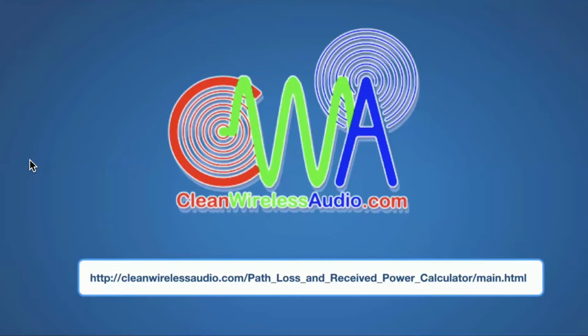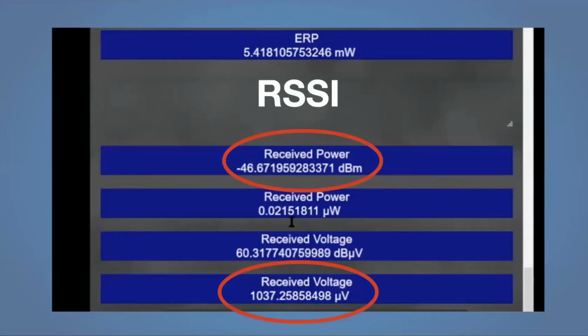So this is a way to get a very complete link budget. Now, some of these things, as he pointed out, you don't have to put all of these things in there, but you won't get, of course, as accurate a link. And what Jason was doing there at the end was saying, well, my signal at 1500 microvolts is a whole lot stronger than I need. So how far can I stretch out? How far will that antenna still give me rock solid? So when you're designing a system, you have some play. Go back and change the distance until you run out of what you consider to be a good amount left.